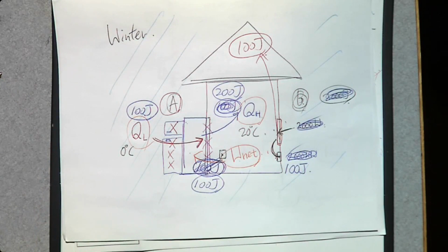Makes sense? So having a heat pump is more efficient than a conventional heater. Having a giant refrigerator with the door removed, placed outside, would make your neighbor look at you as stupid, right? It looks very stupid. However, it is very efficient, because you consume electricity that becomes heat, and you absorb heat from outside that becomes heat in the house.